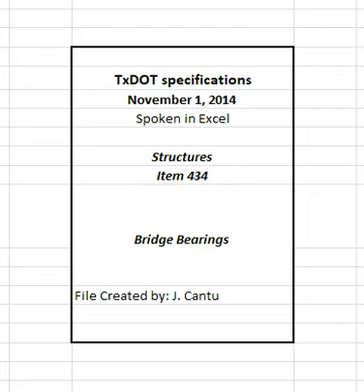2.2.2 Upper component. 2.2.2.1 Steel top, sole, plates. Provide steel top, sole, plates in accordance with the plans, and finish to ANSI number 500 or better on the surface interfacing with the stainless steel sheet. 2.2.2.2 Stainless steel. Provide type 304 stainless steel sheet in accordance with ASTM A240. The thickness must be at least 1/16 inches unless otherwise shown on the plans.